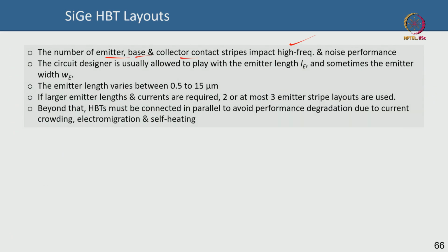So the circuit design, okay, so that's why you have an impact on high frequency noise performance, we know that. The circuit designers generally play with the emitter length. I told you, and emitter width is typically not a given parameter to play with.